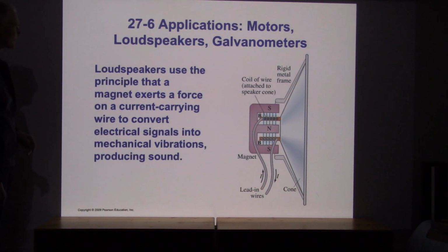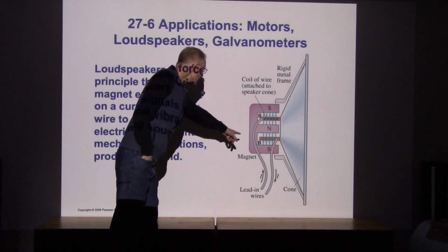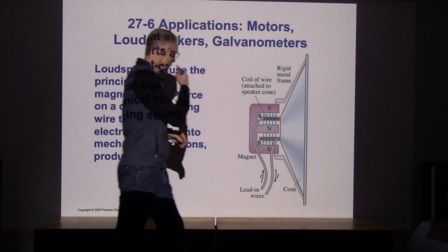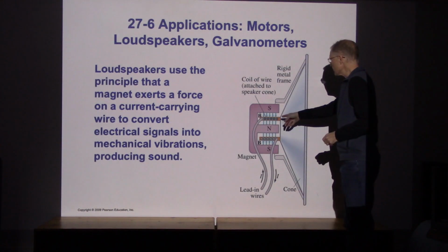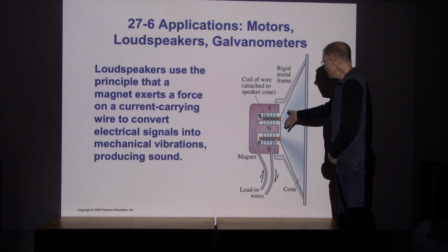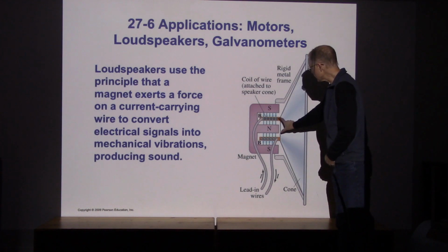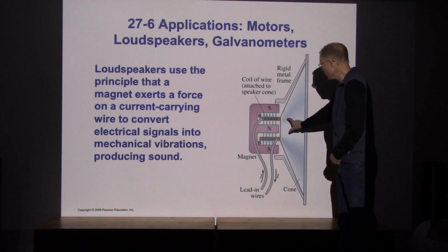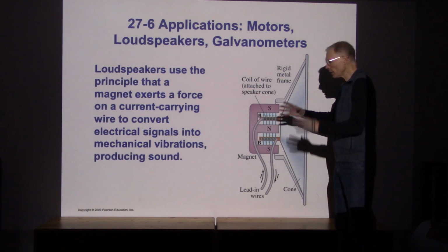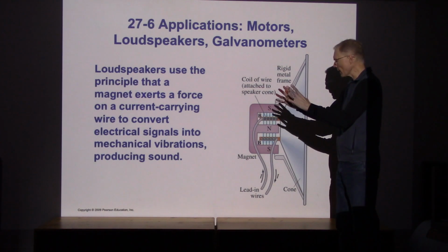using these magnetic effects. And what we have here is a speaker wire. So we have the wires leading into the speakers, and as the current varies, we increase and decrease the magnetic fields that are inside here. So the speaker has magnetic material in it, and the speaker is pulled in and out through this magnetic field as the current comes through. So the current's coming through here and it's getting pulled in a particular direction back and forth.